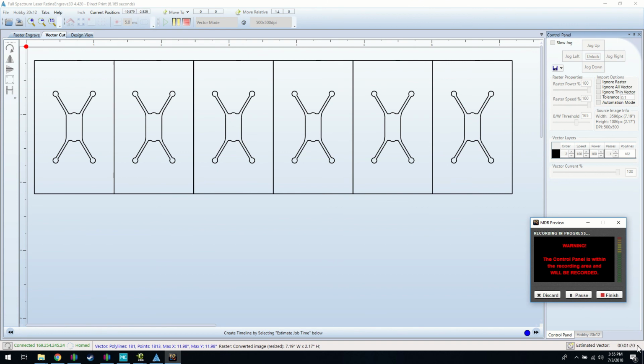And then you want to make sure that those parameters that you've set for vector current, power, and speed over here will actually cut through the material that you've placed in there. Obviously, the thicker the material, either the slower speed you should go or multiple passes. In order to have a crisp, very thin curve to your laser cut line, you want to cut at fast speeds and maybe do multiple passes instead of a slow speed and 1 pass.